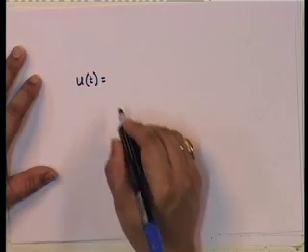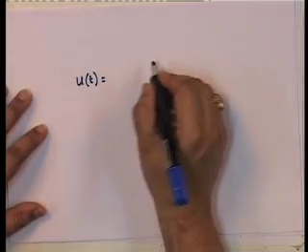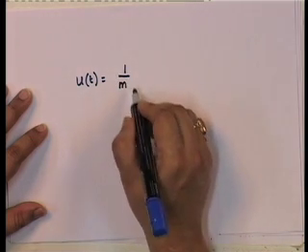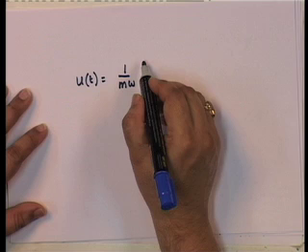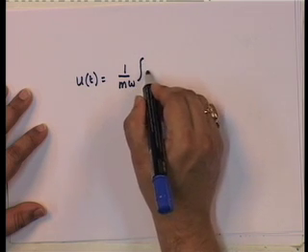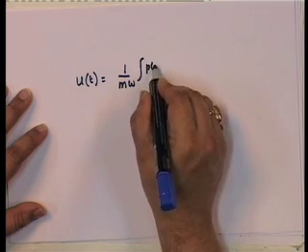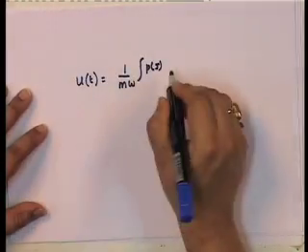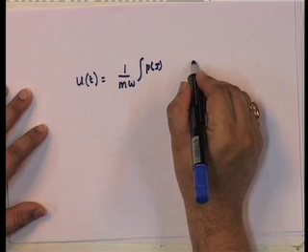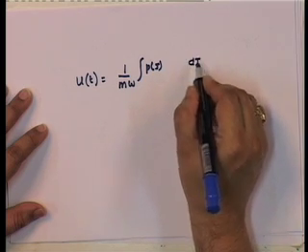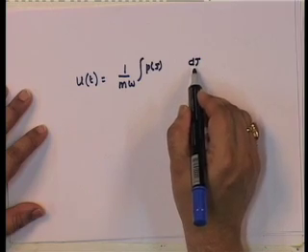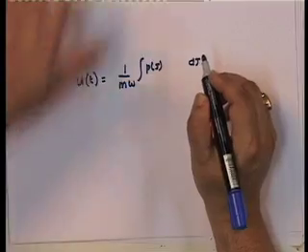So, if I did that, let us look at each individual load, what would u of t be equal to? u of t would be equal to 1 upon m omega into p of tau d tau, because I am finding it at a particular time tau. Okay, this is the impulse, p tau d tau is the response at that particular instant of time.